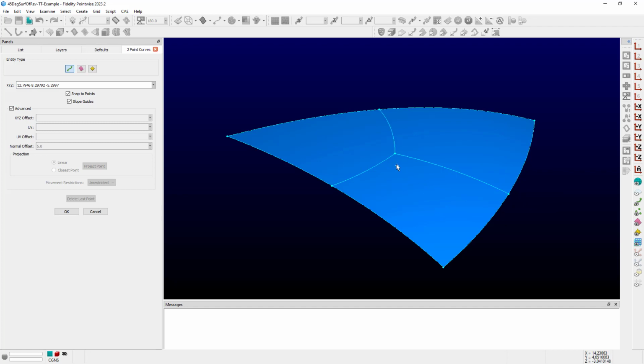And then what I want to do is just simply come up here, select this existing node. Because that node does lie on or is constrained to the underlying geometry or database surface, Pointwise recognizes that immediately and makes this normal offset frame available.